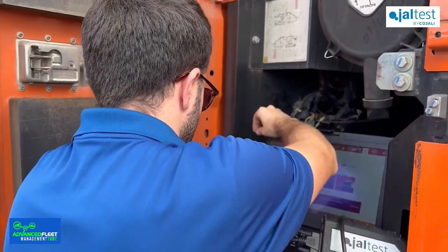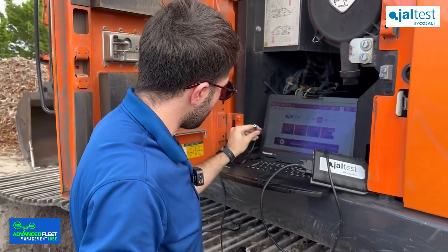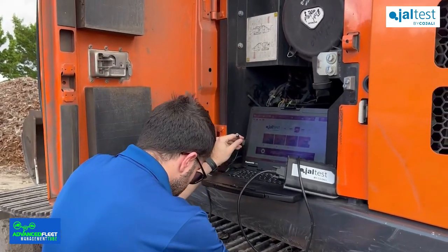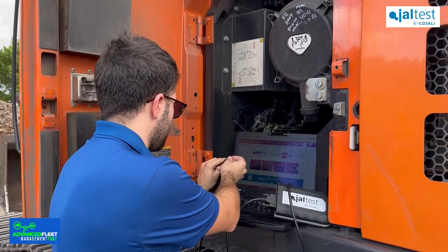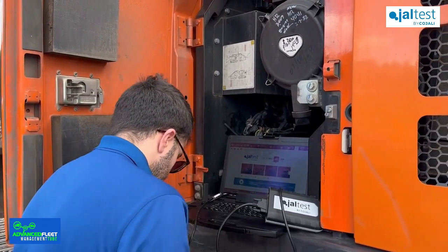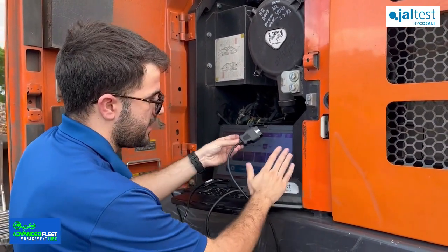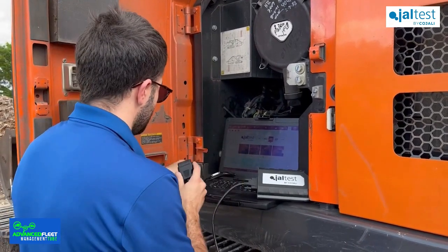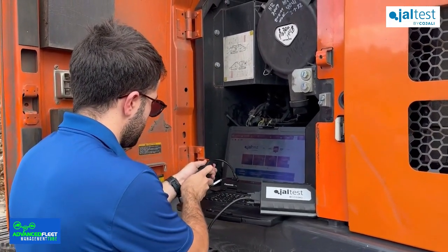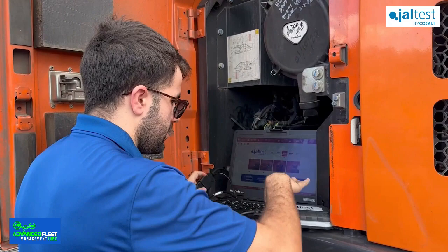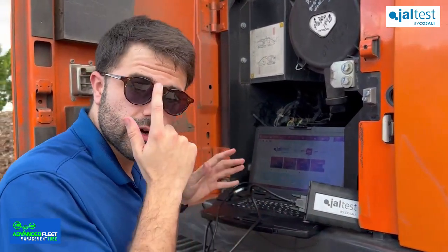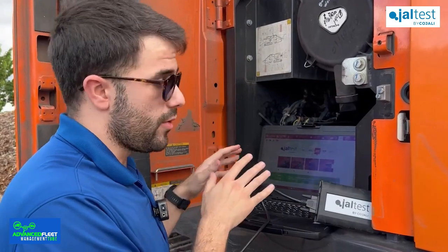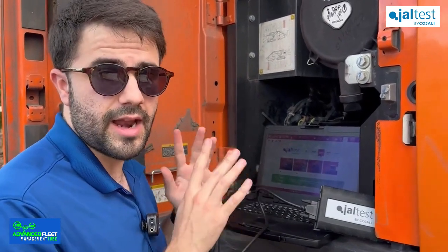All right. Then we are gonna need to put power supply here. So for that, I already placed the gators in the battery to feed the connector. And then as always, we are gonna feed the link using the OBD2, okay? So we place it here. All right, there we go. And now it's time to go to the software, look for off-highway, heavy-duty, Hitachi, and our model, okay?